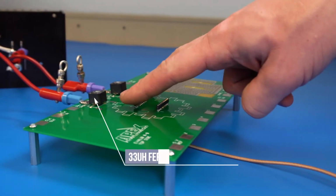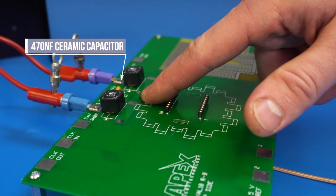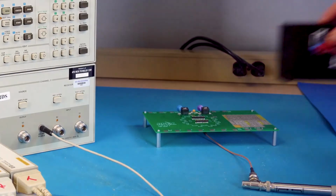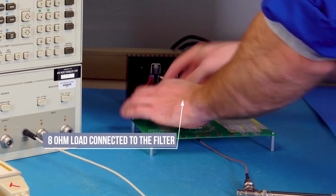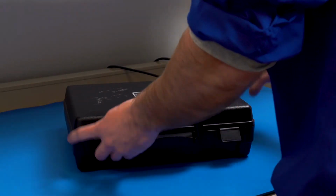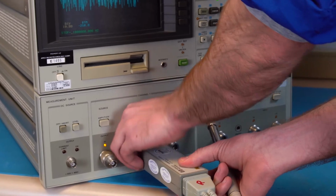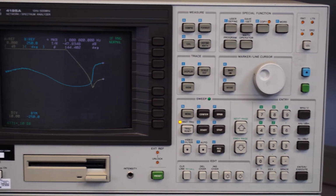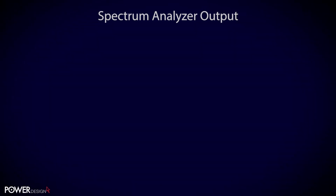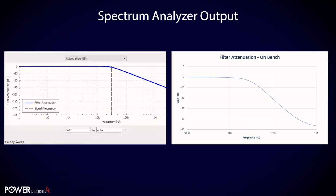I built the filter using 2 33 microhenry ferrite core inductors and a 470 nanofarad ceramic capacitor. Our 8 ohm dummy load is connected to the outputs of the filter. Even without plugging in an amplifier, I'd like to sweep the frequency and take a look at both the transfer function and impedance on this spectrum analyzer. Here we can see the transfer function, which matches very closely with what we saw in Power Design.